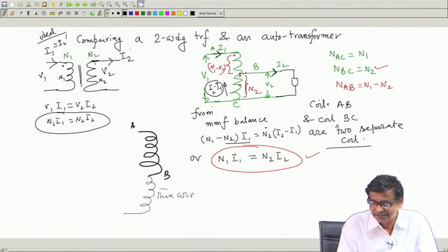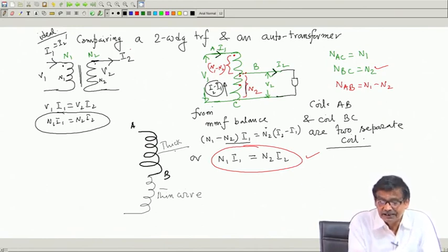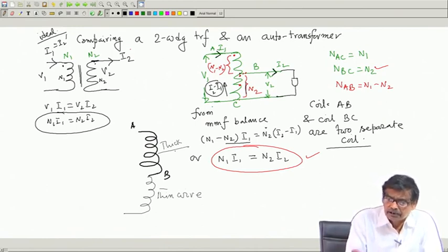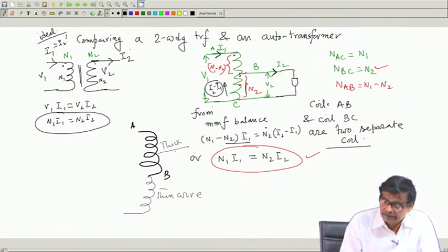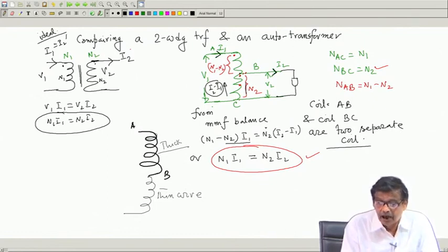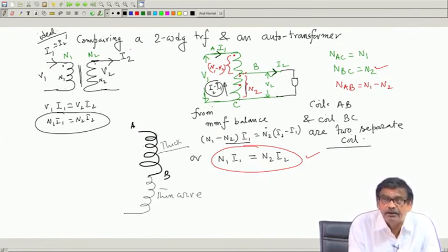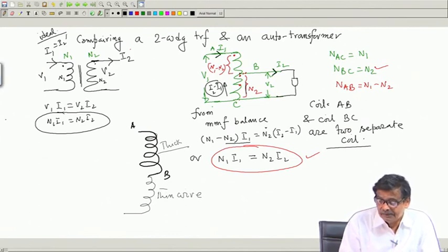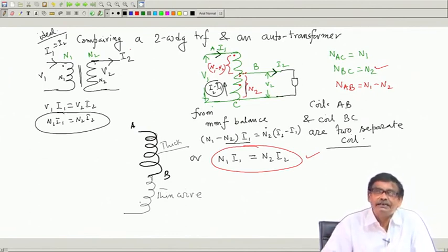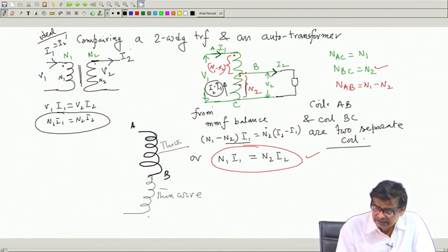This is crucial to understand. This should be thick. Unlike a two winding transformer, I 2 whatever load current you are delivering, that will decide what it is. If it is large, this sectional area will be more. But here in this portion, the sectional area of the upper portion will be same as the sectional area of this two winding transformer here. But for this portion, I can make it thinner. So, it looks like this point is C, thin wire, this will be thick wire.